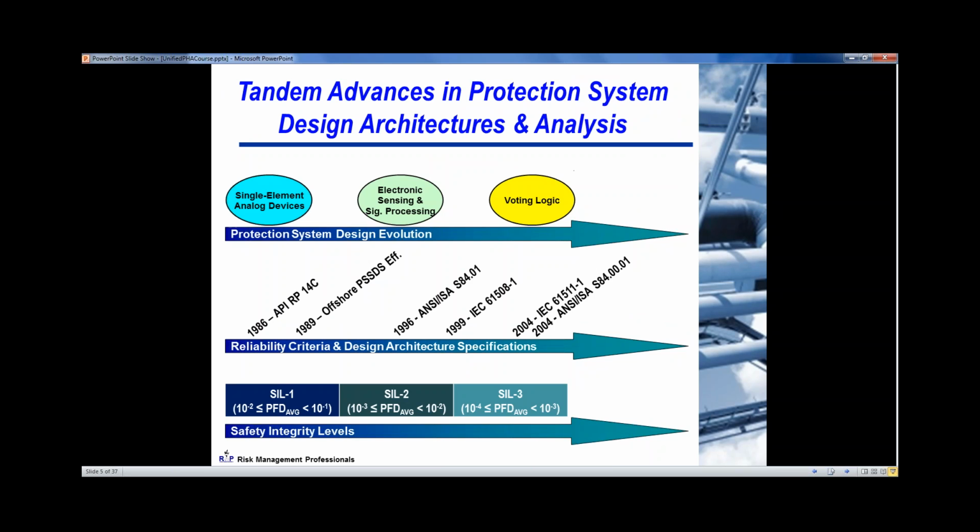Helping make decisions on where you invest your money for the type of reliability that you want to achieve, and whether the reliability is satisfactory, is very important. The HAZOP and LOPA techniques push you in that direction. So from a cost-effective implementation of key safety systems, the quality of your HAZOP and LOPA is also very important.